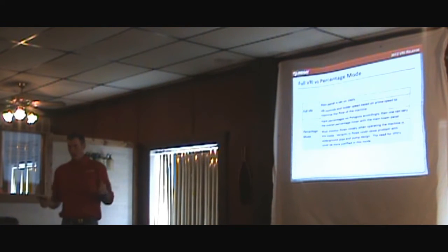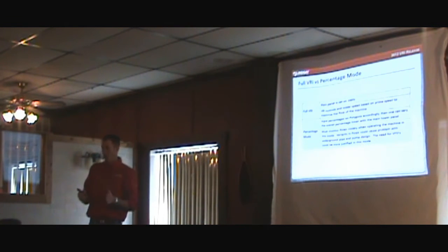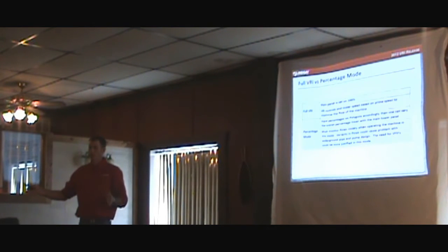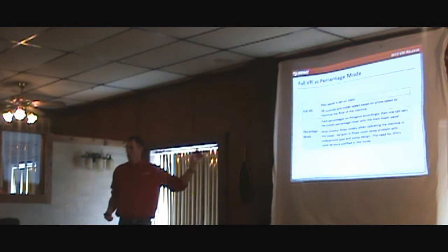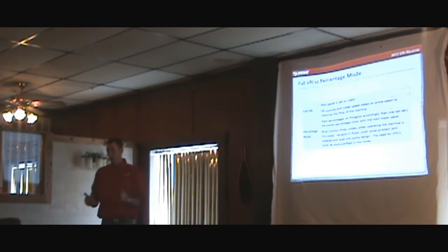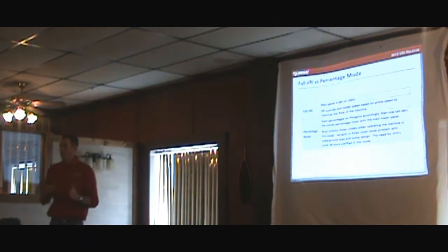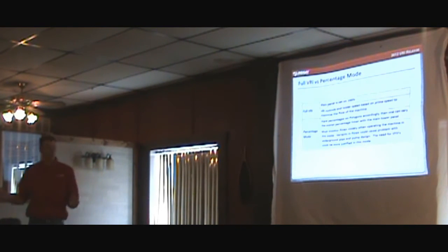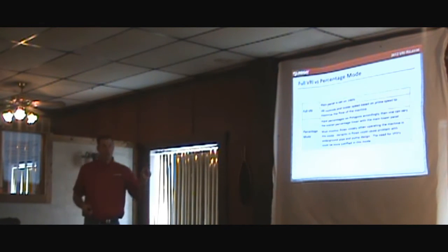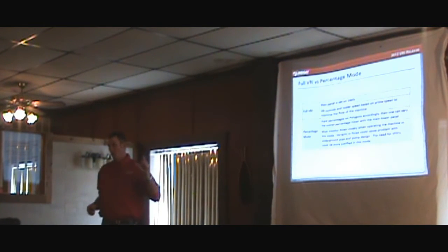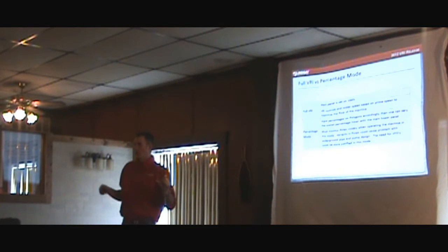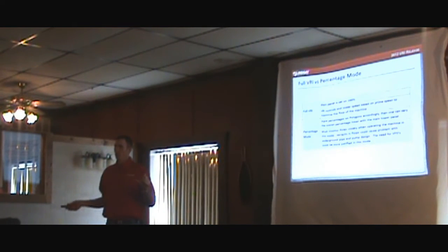If you only have VRI on, say, 3 or 5 spans, which we can do, you don't have to put it on the full 7 towers. You have to run it in percentage mode. What I'm about to explain, you can't run unless you have nodes on the entire machine and valves on the entire machine. Are we good so far? Okay, so full VRI. In full VRI, we control the travel speed of the pivot. You do not input percentages, you input rates.